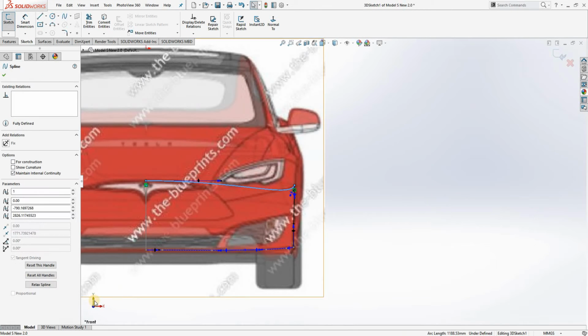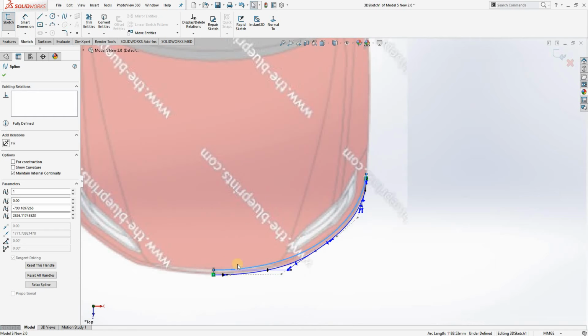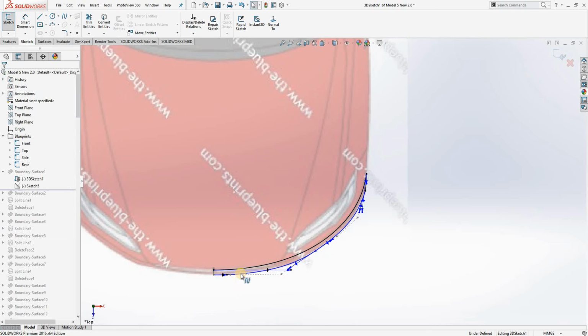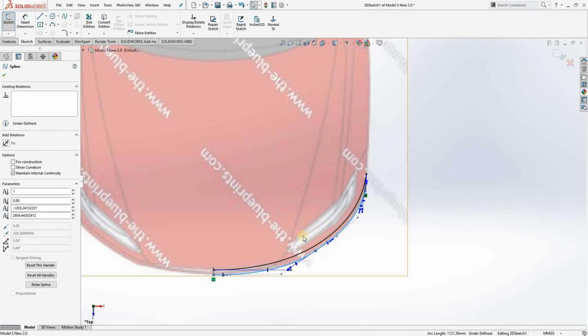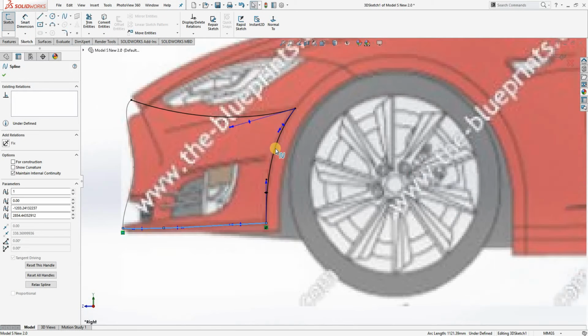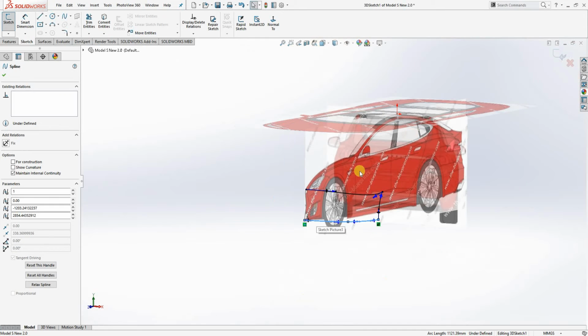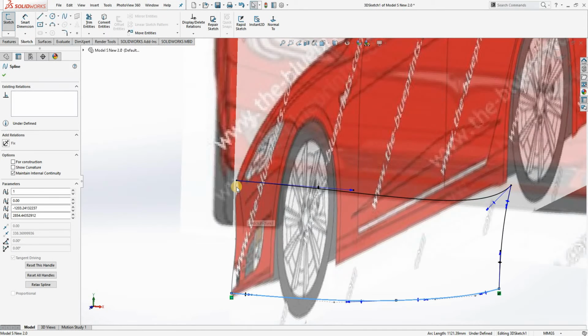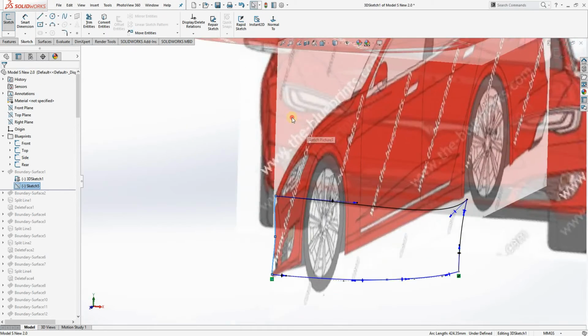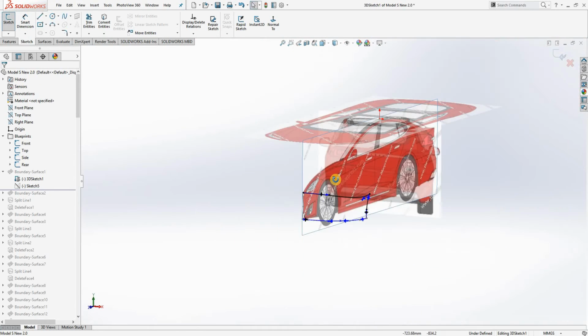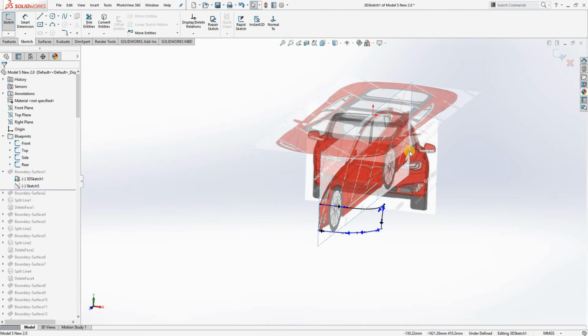This top spline is following the curvature of the top front bonnet of the car, and the bottom spline is following a similar edge on the bottom. And this spline is following a section near the wheel. What I've done, on purpose, is only model half of the car. So all my surfaces initially are going to be on this side plane, because I know this is a symmetrical model. Once I've finished half, I can just mirror and I'll create the full model.